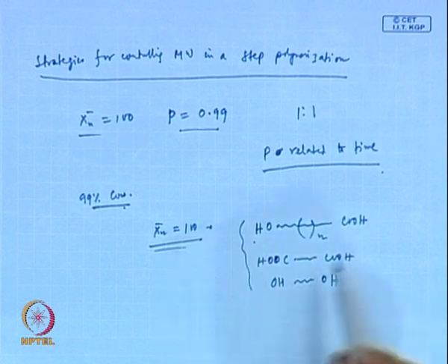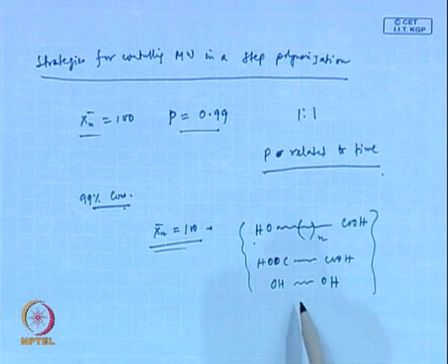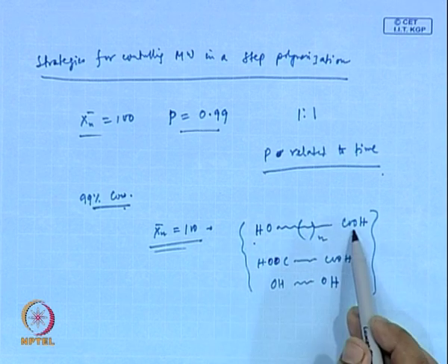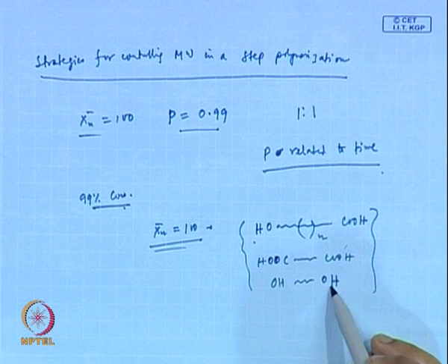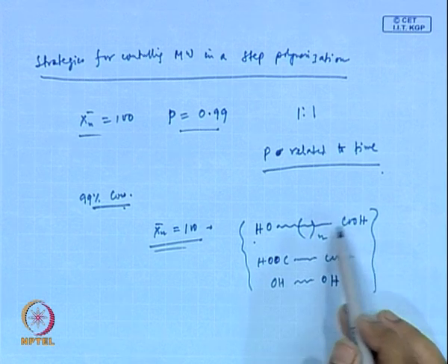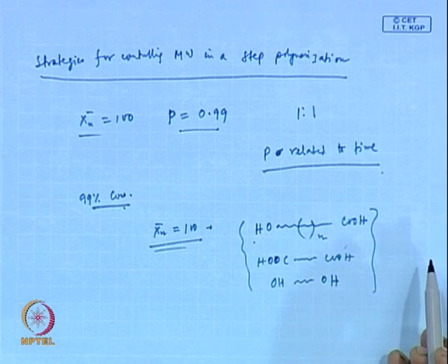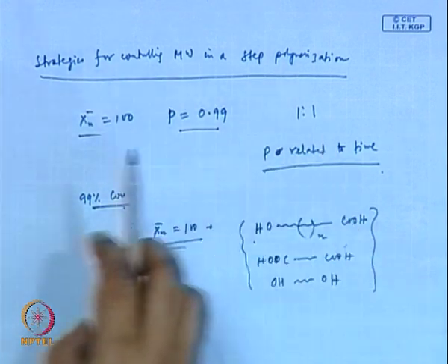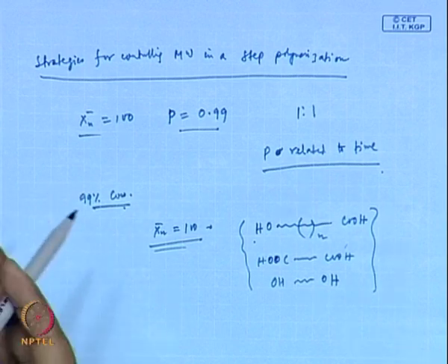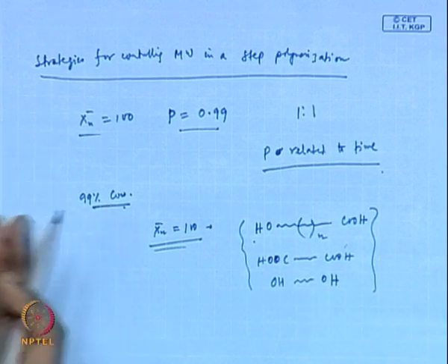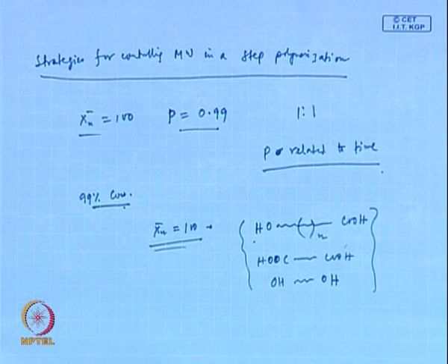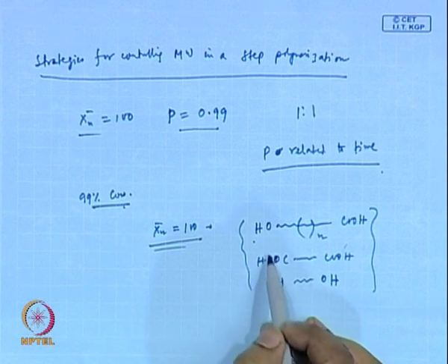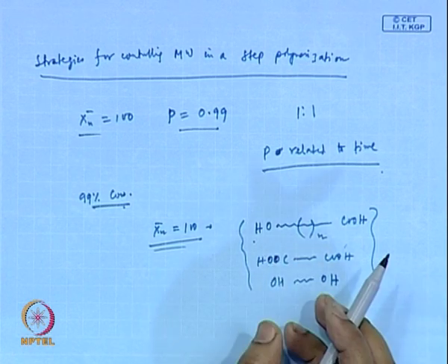So, if you stop the reaction at this level, what you have is still the possibility of these molecules participating in further reaction. So, when you take this polymer at this stage and mix it with other additives and fillers and do a compounding, which is a further process which you do in a melt stage, as I said in the first lecture, then these functional groups are free to react there.